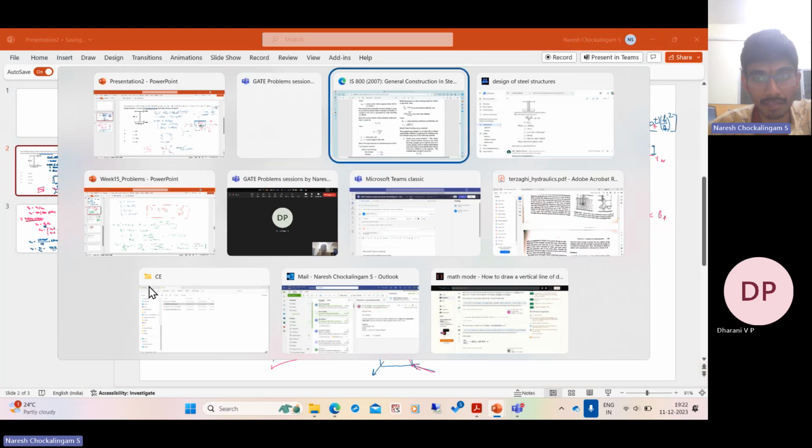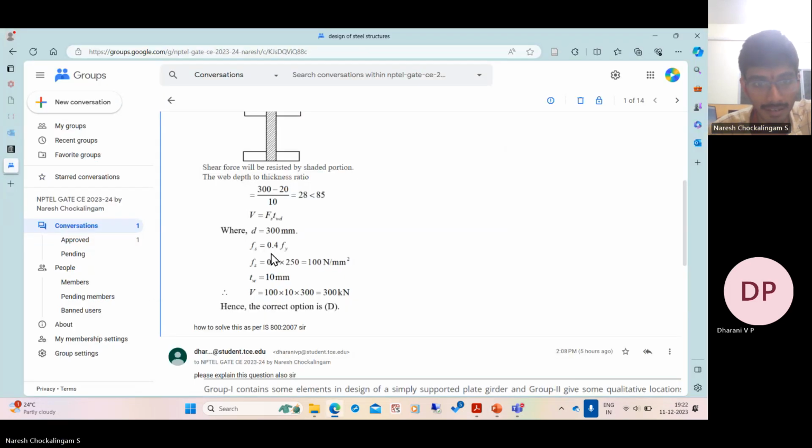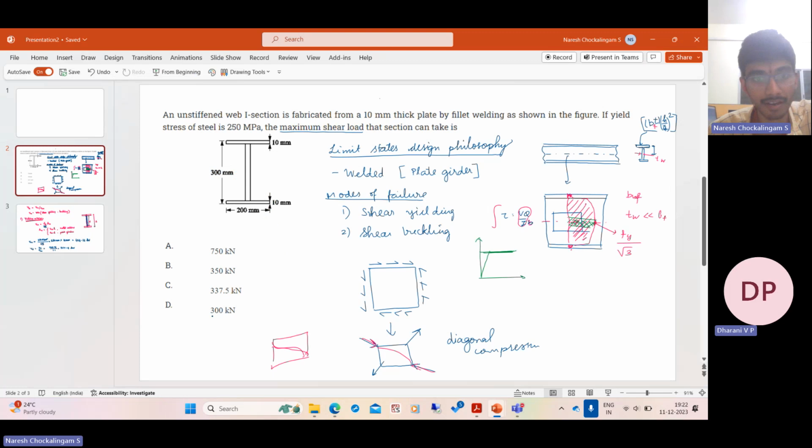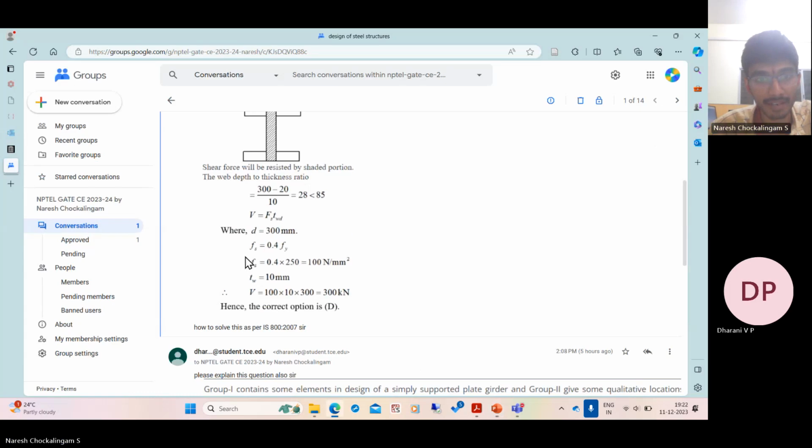So as per the old procedure, what was the answer? Okay, Fs equal to 300 kilonewtons. That is fine because this is according to the working stress method. So this Fs is equal to 0.4, I think it is the factored shear strength, because as per our current codal procedure, it is 1 by root 3, and 1 by root 3 is about 0.57.